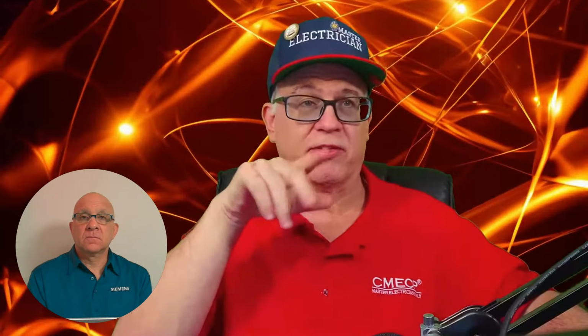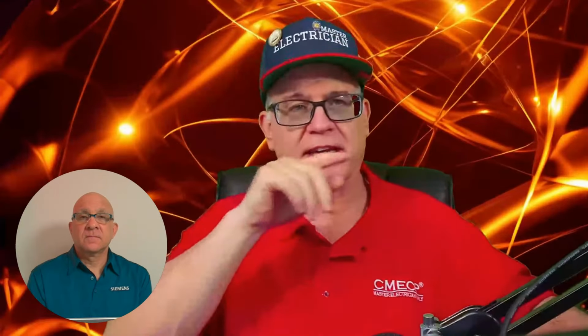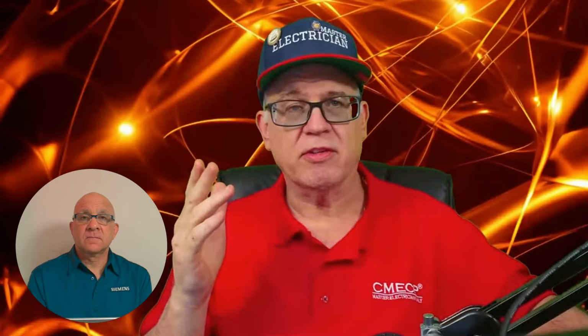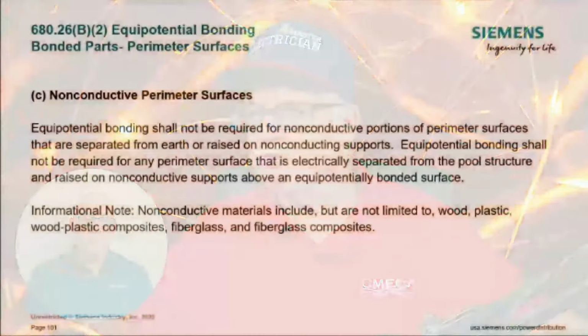In that scenario, it would be pointless for it to be insulated because it's got to be in contact with the earth. What we're talking about is the element of bonding all of the parts together. What I can use is solid copper, not stranded copper, but I can also use 40% copper clad steel. But we're talking about what can be used to connect all these parts together that are required to be bonded together. That's what it's talking about in the first one, B1, right? That's correct. So let's see here.